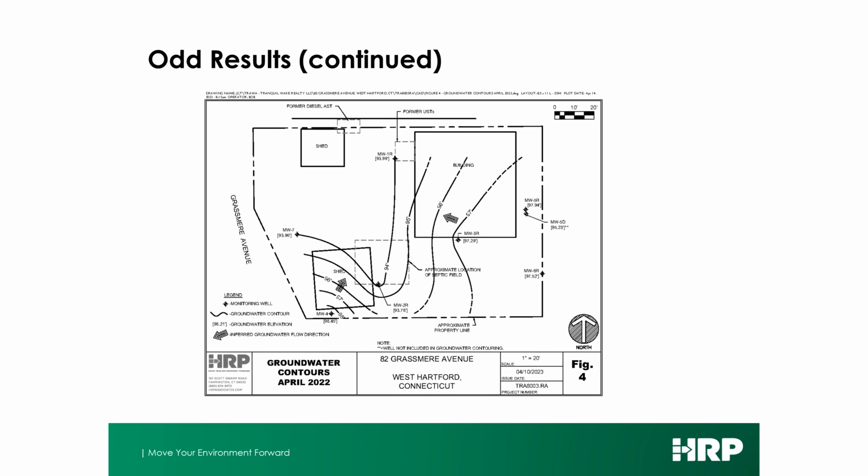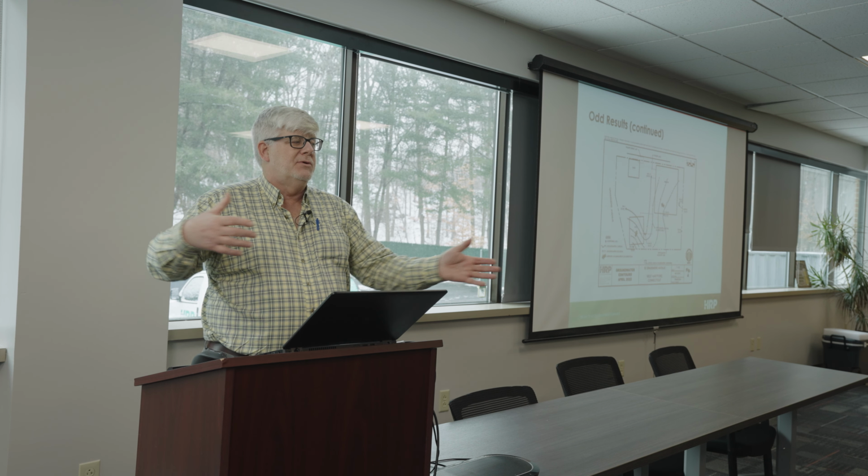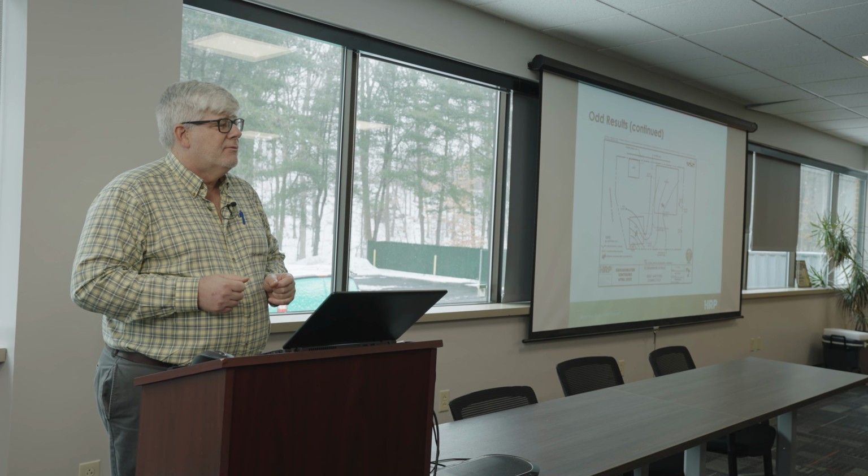And we're seeing stormwater or something getting into that system. The other thing is that out on the edge of the road is the stormwater system, and this is along Trout Brook, which has got flood control, so the stormwater has to get pumped up and out. And maybe we're just seeing the times when the pump system is either down or overtaxed. And so it's backing up in the stormwater system and infiltrating out into the aquifer.